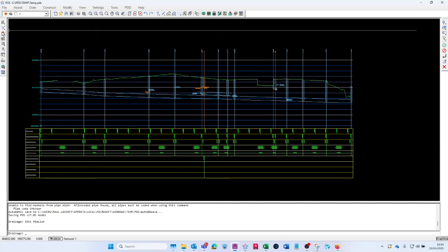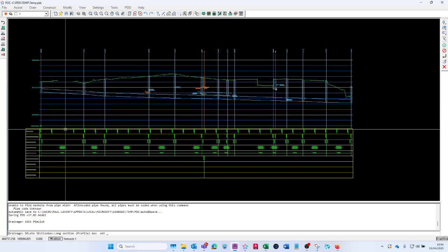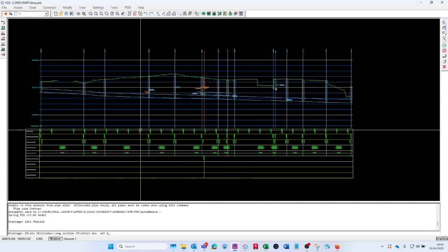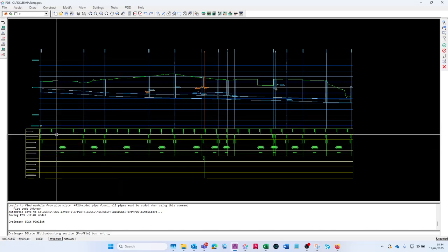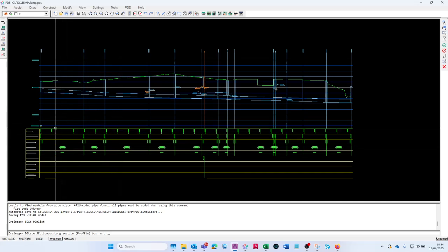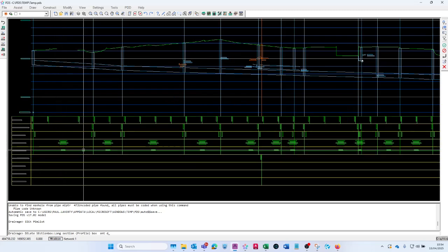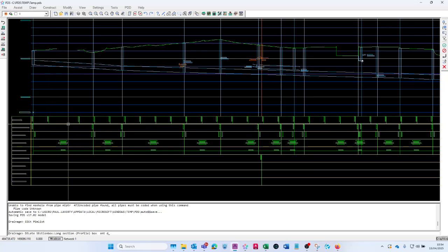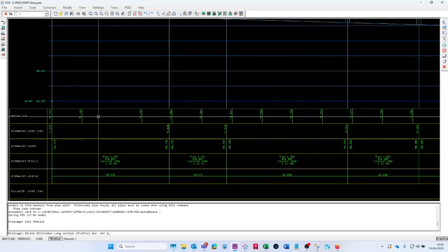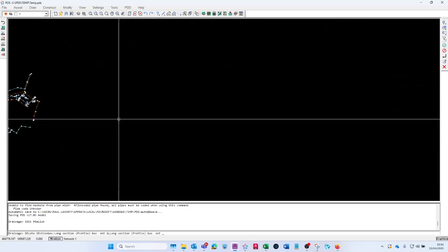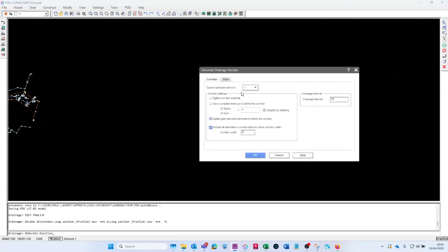So let's stop for a moment and go back to our sections, and we'll go through some of those little tick boxes and everything else. The one with the X deletes the section. The other thing is that when you're editing these profiles, if you're regenerating the information or deleting it or whatever have you, you always have to keep these first two lines, because that's what those two lines get built off. You can generate these profiles with just file, just surface water, or do both, but no matter which option you choose, those two lines are constant because the ground level is always constant. So when you're manipulating these profiles, you select one of those two lines. So let's delete that off. All right, so let's start with the section.